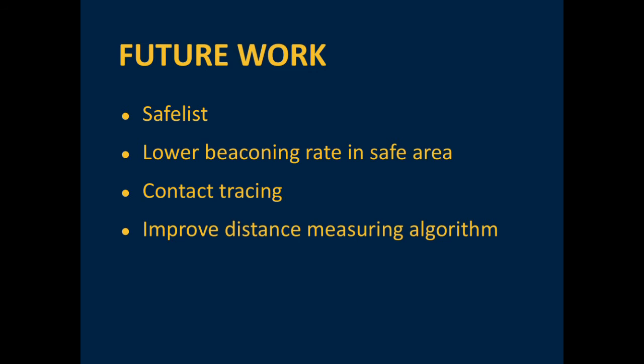Another enhancement for our product could be the addition of contact tracing. To implement contact tracing, we could track a list of devices that caused alerts within the last 2 weeks. To improve the accuracy of the distance measuring algorithm, we could explore dynamically updating the environmental factor to match the current environment and manually calibrating the transmission power from 1 meter away.